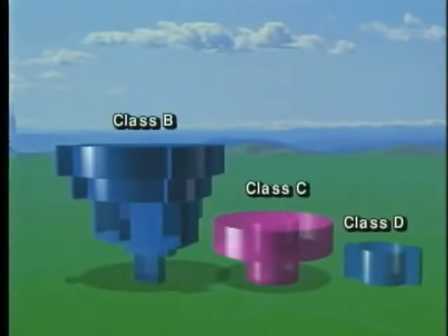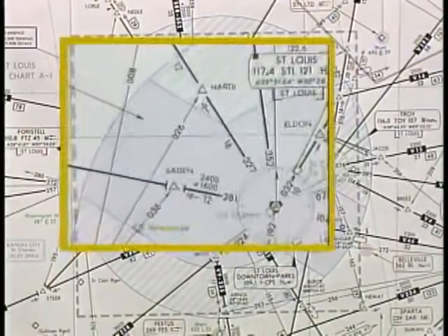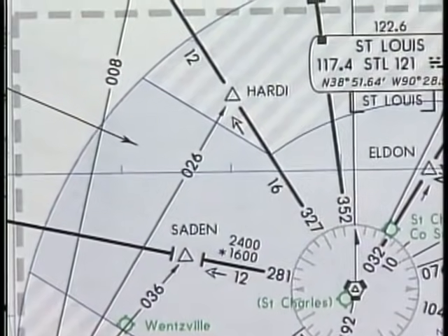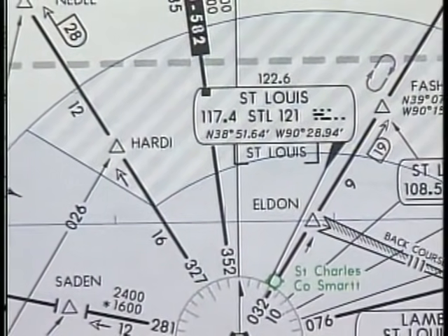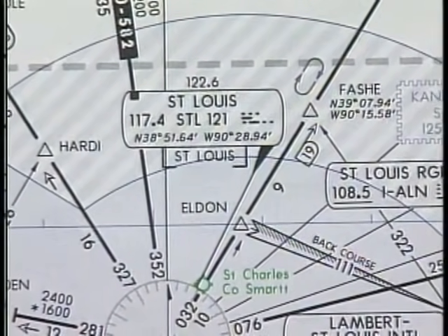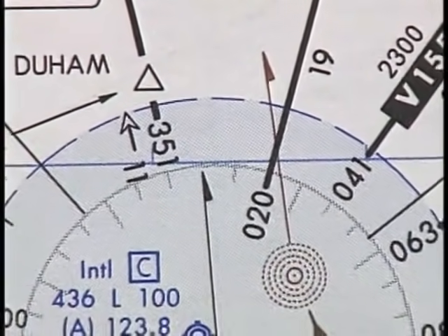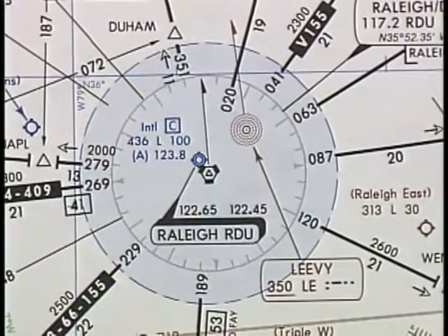Terminal airspace areas that require communications are indicated on NOS en route charts. For example, Class B and Class C airspace areas are depicted by blue shading around the primary airport. A solid border indicates Class B airspace. The white and blue cross-hatchings surrounding Class B airspace areas depict the 30 nautical mile Mode C veil. If the blue shading is enclosed with a broken border, it is a Class C area. The border represents the general size and shape of the upper portions of the associated controlled airspace.